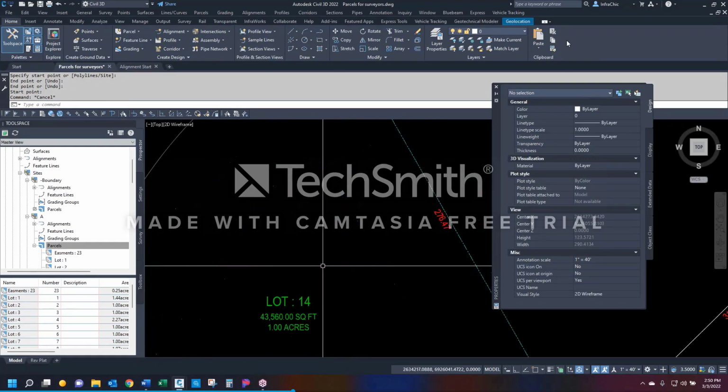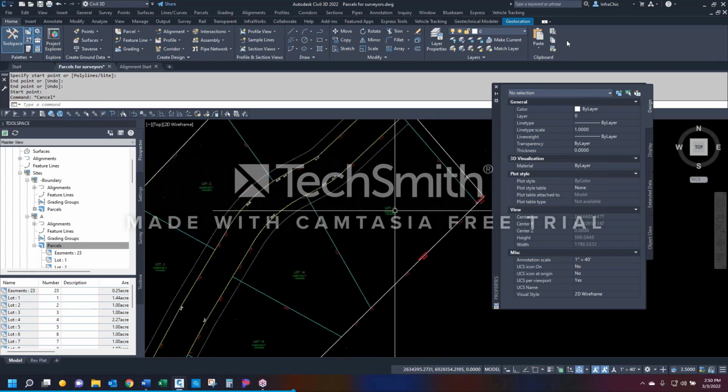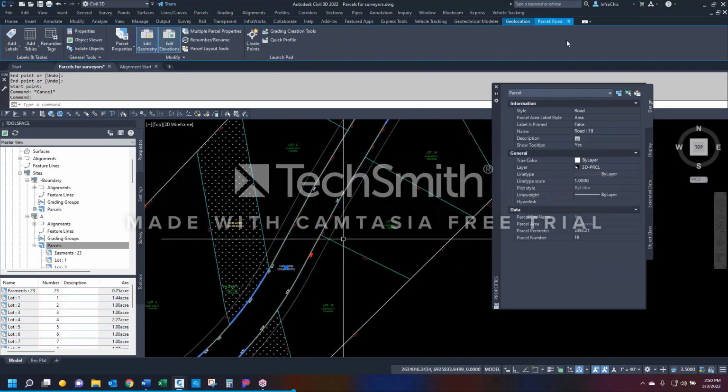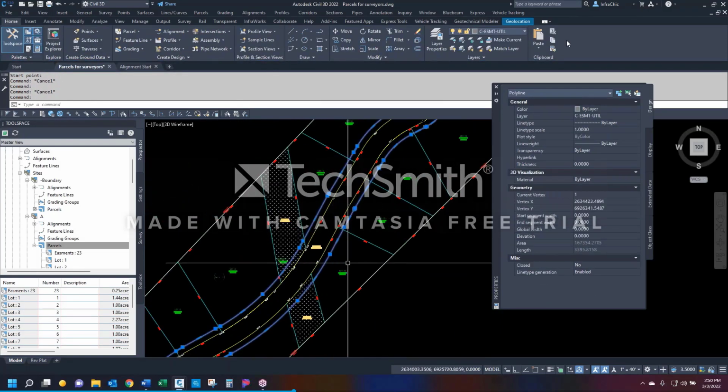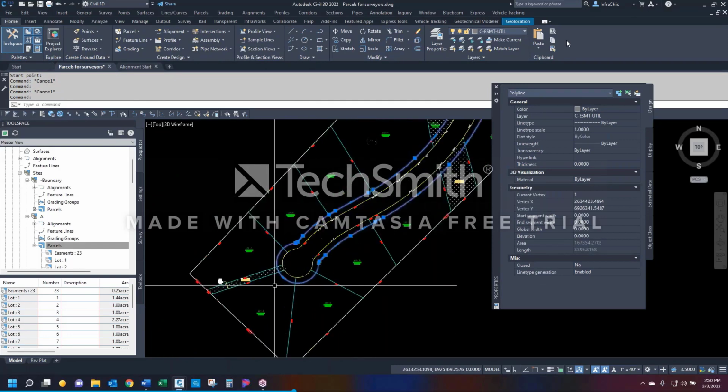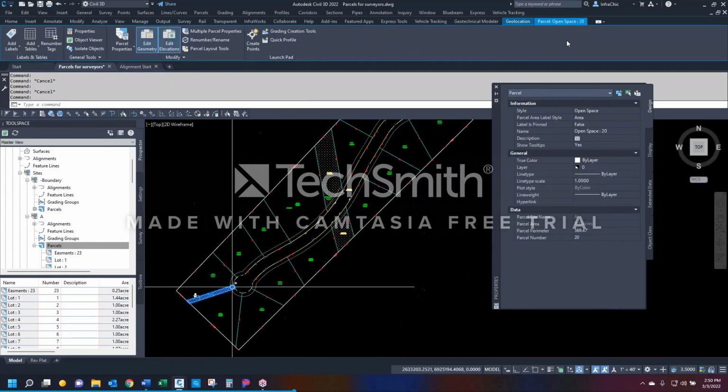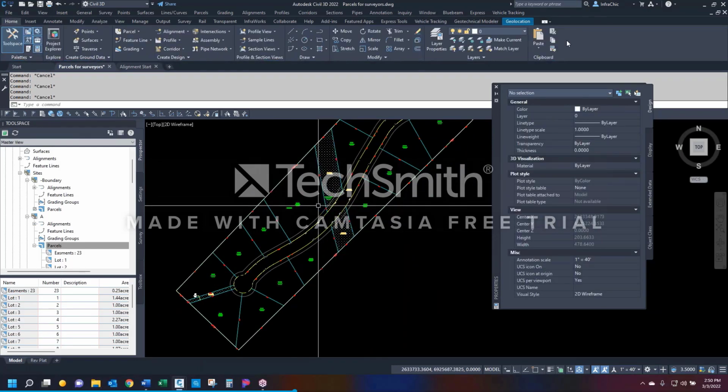They are an acre in size or more. Okay, we have a roadway, which is 60 feet wide. We have dummy line work in here meant for the 20-foot wide utility corridor. And we have the easements for the drainage easement and the pipeline easements both in play. That is an acceptable preliminary plat to get labeled up and started with.